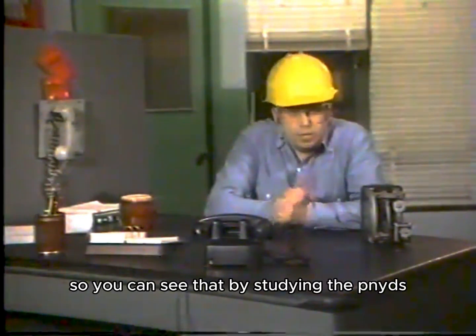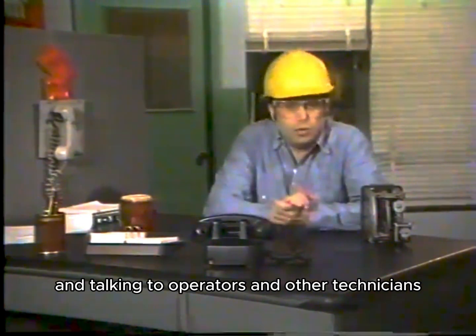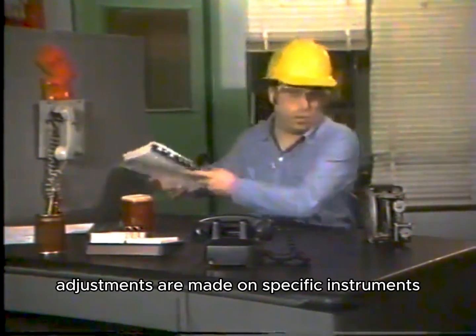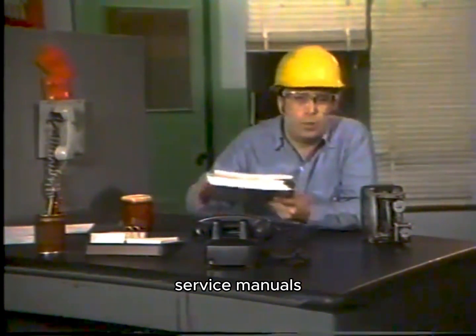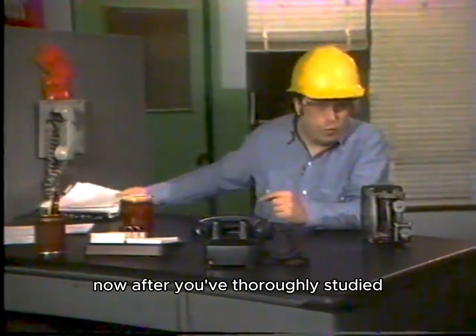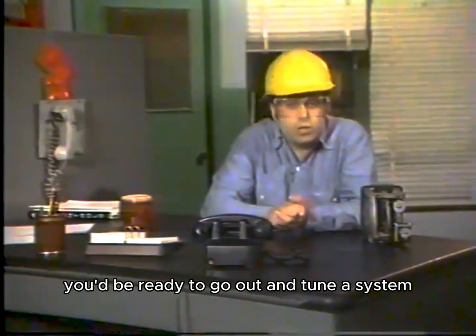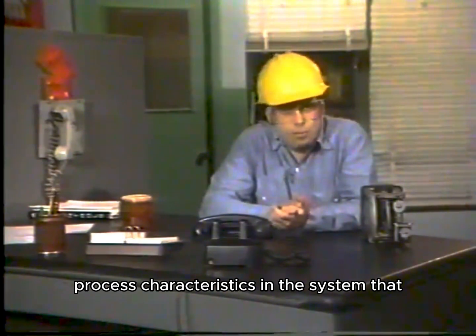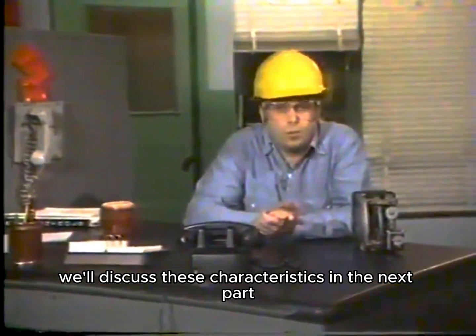So you can see that by studying the P&IDs, control logic diagrams, calibration records, and talking to operators and other technicians, you can learn a great deal about a system. But when you want to learn how adjustments are made on specific instruments, you would refer to the instrument manufacturer's service manuals. Now, after you've thoroughly studied all the documents that we've mentioned, you might think that you'd be ready to go out and tune a system. But you should also be aware that there are process characteristics in the system that impact on its response to a disturbance. We'll discuss these characteristics in the next part of the program.